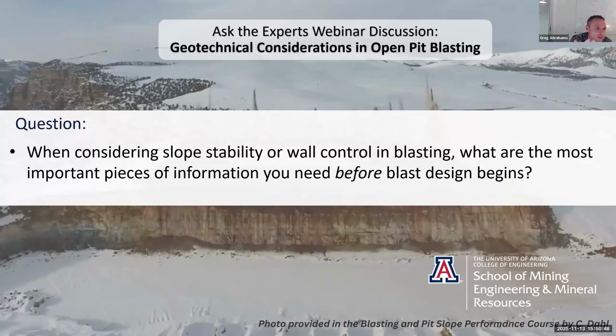And even looking at this picture in the background, if you're working in -40, doing complex loading is miserable. I've done it, and it's horrible. And I think trying to come up with a design that can actually be implemented is critical, especially if it's a new concept. You're coming in, and you're saying, look, we have to change our practices. Production's fine, but we're just killing the walls here. The blast design needs to be as simple as it can be for the crews on the ground.